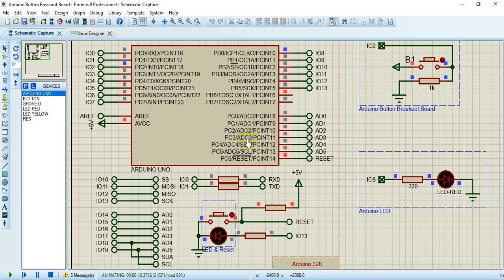And this is the LED at pin number 8. When you drag and drop this block, the connection is done automatically for you. If you want to change the pin connection, you need to modify it. I'll show you one complete example after this. I will implement complete lab number 4 by using the drag drop play method, so you'll get more idea how to work with this Proteus software using a graphical approach.